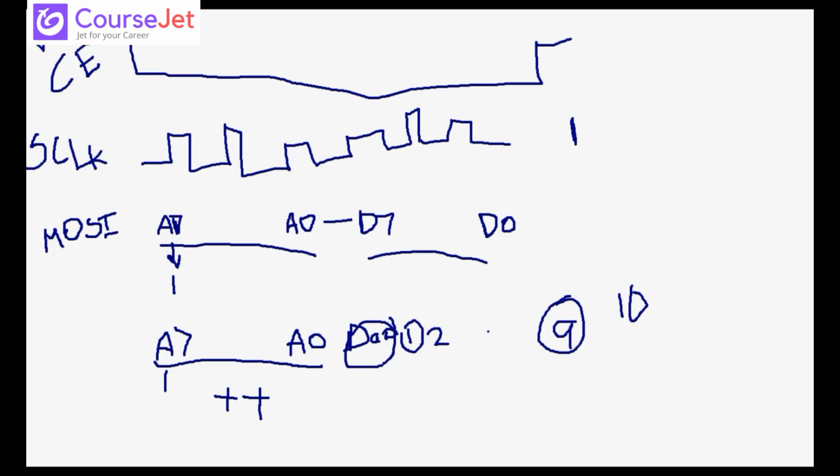Similarly, if you have a reading option, the same thing follows, but here you need to make this A7 bit 0. When you make the A7 bit 0, it will understand that you are doing a reading operation and not a writing operation. That means, for example, if I have a file or data at a particular location in my memory card, an SD card connected to my microcontroller, and I want to fetch that data.